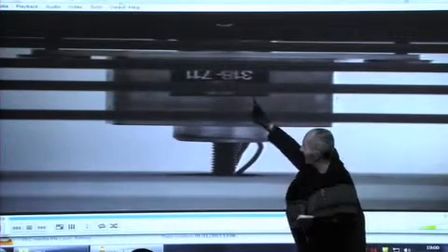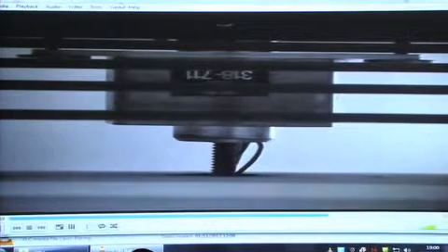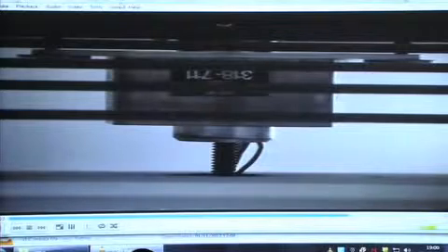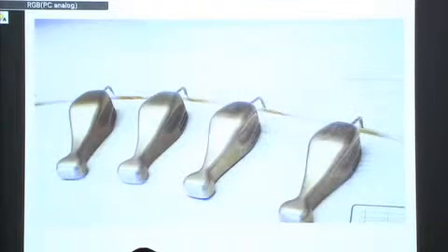So this was trying to connect analog and digital. So all of these... this linear motion is made by these stepper motors which are moving rods up and down. The stepper motors, strictly called stepping linear actuators, have a worm screw. You can see that threaded rod. Inside there's a motor that's driving the nut effectively, accurate to 0.05 of a millimeter. So you can program it to move the rod up and down. So that's a digital driver, and the output is a wave. For the sake of this particular demonstration, it was animated. There was no reason particularly why they should be moving simultaneously. The intention was just to achieve a particular shape.